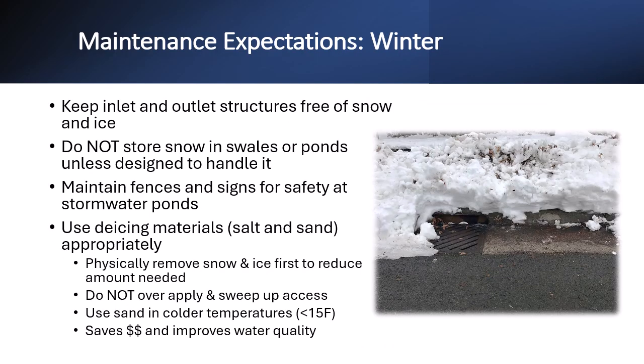Winter conditions require specific consideration for stormwater maintenance. Keep inlet and outlet structures free of snow and ice. Melting snow is stormwater and needs a place to go, or there can be problems with flooding. Do not store plowed snow in swales or ponds unless they are designed to handle it. Since snow often contains dirt and sand, if it is stored in a swale or pond, the meltwater will likely overload the feature with sediment and will need cleaning out in the spring, increasing maintenance costs.